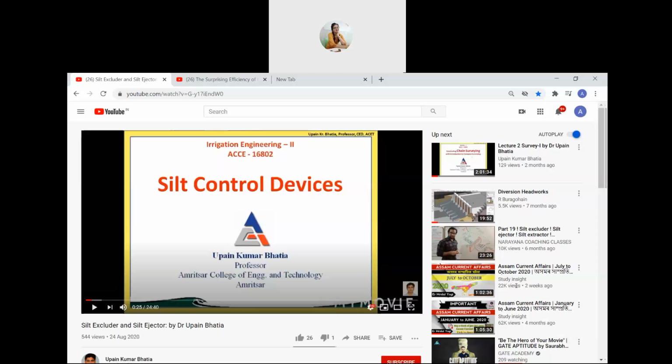Okay, so now coming to the devices. The circle represents the location where the device will be provided, and the number indicates its category. Okay, so the first type of structure will be provided within the river. So this location is within this river only, but it is on the upstream side of this canal. So the canal head regulator is provided over here. So on the upstream side of the canal head regulator, this category 1 structure will be provided. So this is provided in the river only.